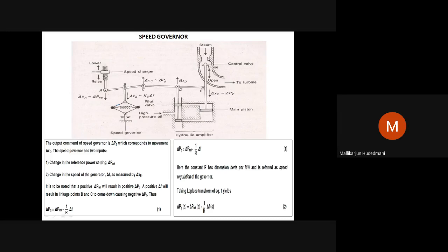That's all. Suppose you want to work according to the fall or rise of RPM due to load changes. At that time you use this feedback method. That's what I'm speaking. Change in reference point is one mechanism to increase or decrease the fuel input. Otherwise, a change in speed of the generator, that is frequency, will be reflected by this governor feedback to the other side. Whatever droop I am speaking of is concerned with this area. So this will respond in proportion to the characteristics mentioned.